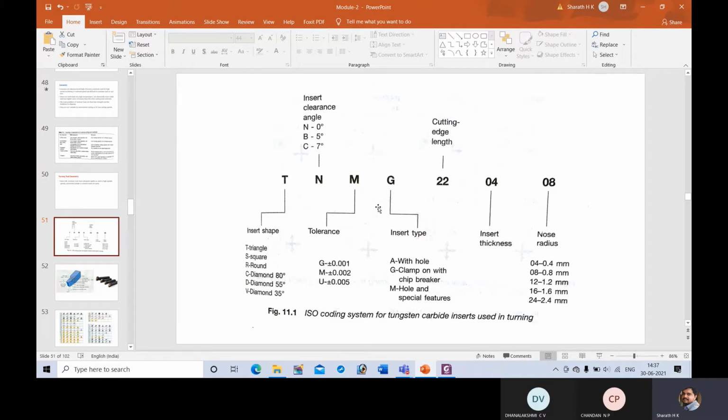Based on the properties of the material of the work part and the contour that you want to get, you can go for picking the tool inserts, and again the operations that you need to perform, whether it is turning or drilling, whether you are removing material internally or externally. There are many considerations in drilling also, countersinking. Based on that, you can choose the tool inserts.